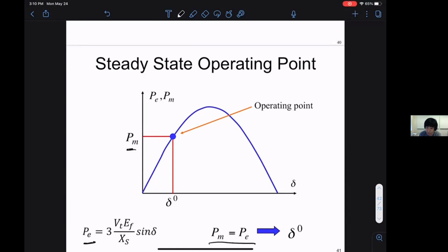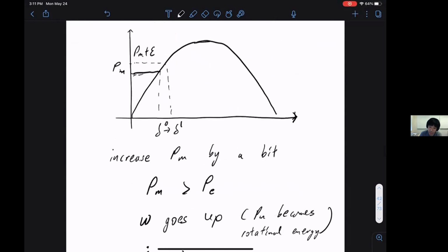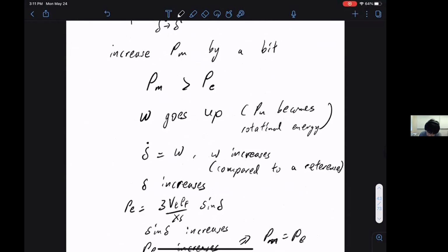But for a larger bulk power system with thousands of nodes, it's actually quite difficult to figure out whether it's stable or not. That's a very active area of research, to formalize this picture for a larger system. That's actually quite hard to do. We don't have a very good idea how to do that right now. But for a small system, it's a very clear rule: less than 90 is stable.